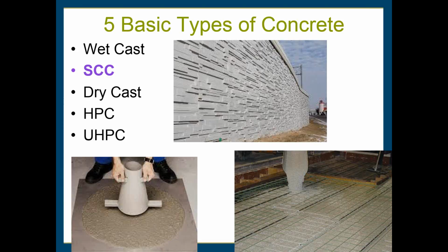SCC also has less coarse aggregate than wet cast, and a greater quantity of fine materials, in addition to the use of admixtures to achieve that flowability.